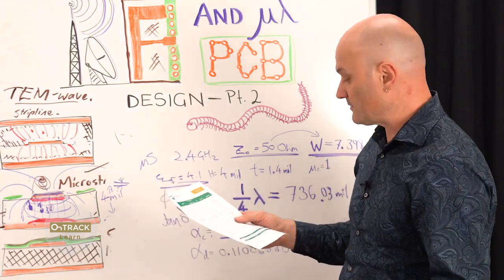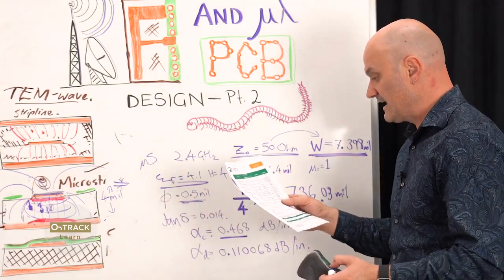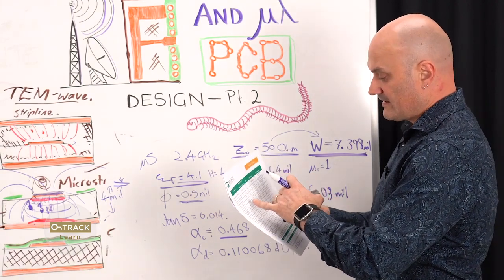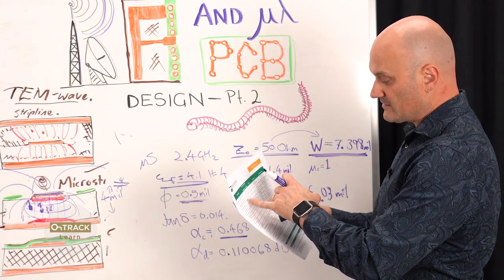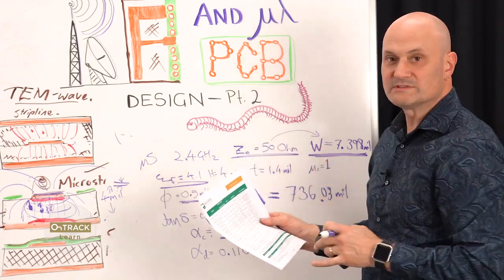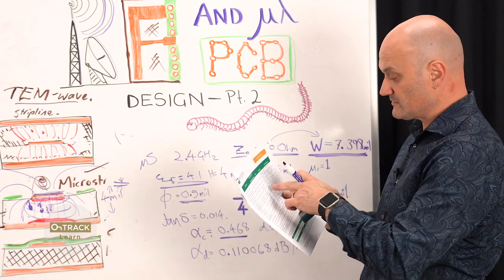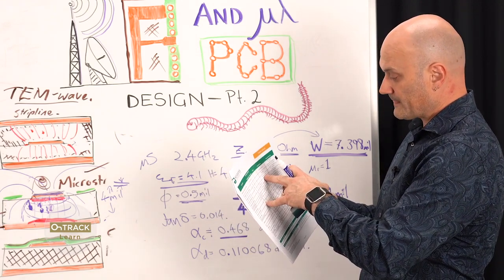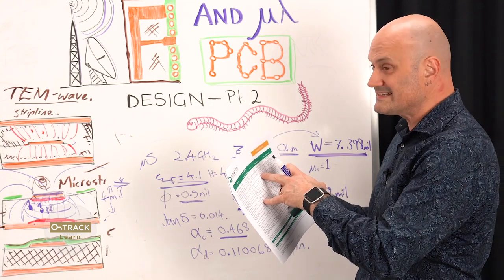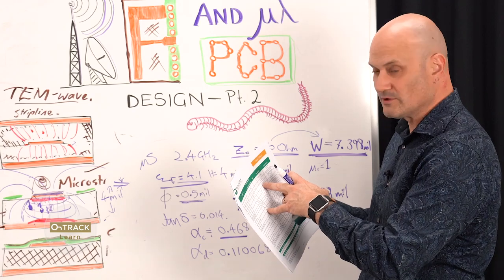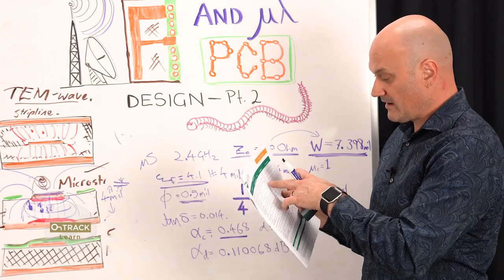This is just one example. So I have a Rogers data sheet here, and what I like about these is that Rogers tests things like their dissipation factor and dielectric constant at the frequencies the material is intended to be used for. So here, dissipation factor tan D, they test it at 10 gigahertz, not 1 megahertz. It's several orders of magnitude higher frequency.